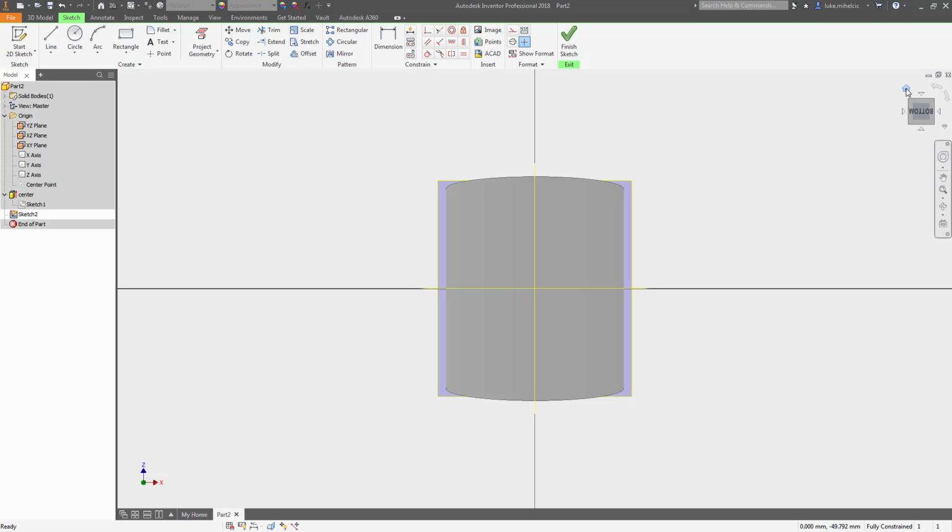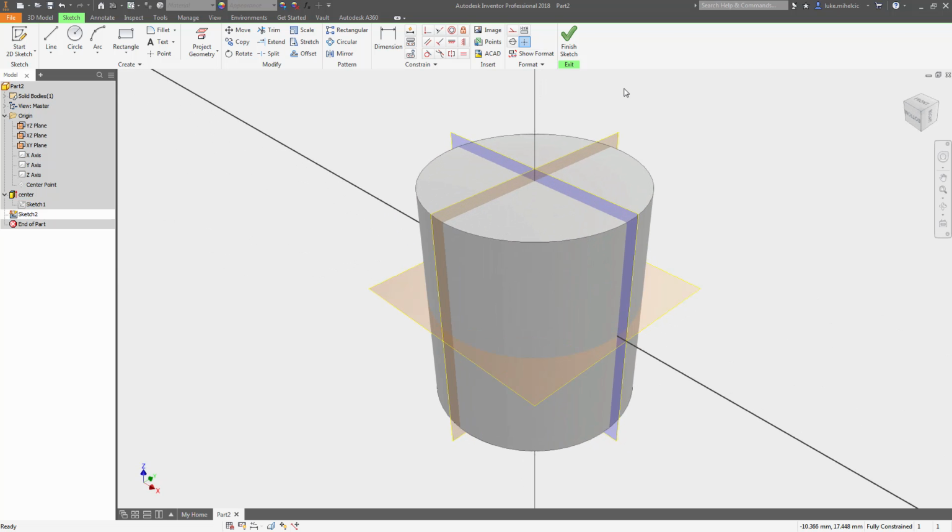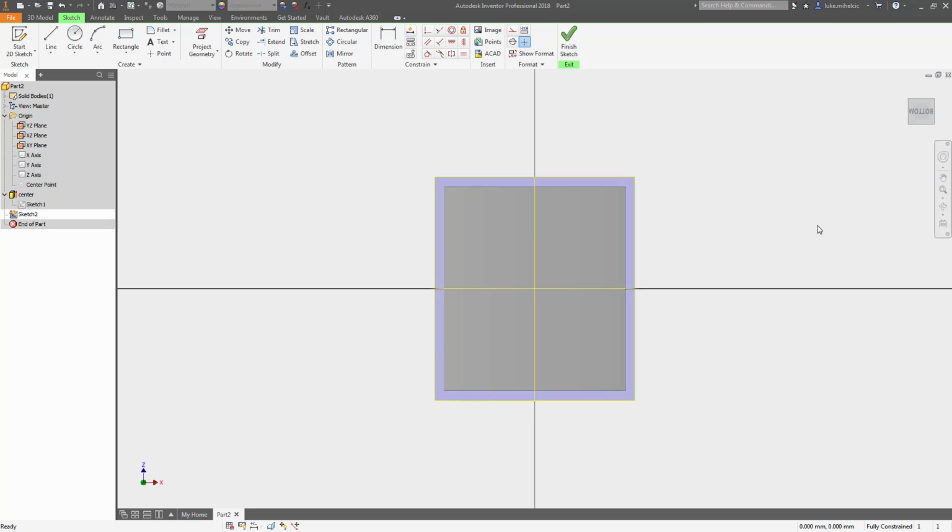If you right click on your home key in the upper right hand corner and I do perspective with ortho edges, what that does is anytime I'm looking at this orthographically, front, top, right, bottom, all the default orthographic views, it flattens it temporarily. So if I hit F6, it's an isometric view. If I go to my front view of this, it flattens it. Really nice way to adjust this.